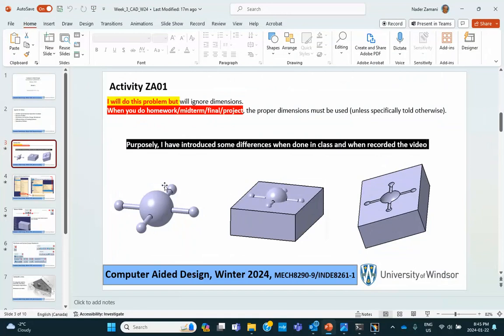So the part that we want to make is actually over here. Here is the mold, and obviously there's a gate here where plastic is injected, but I'm not going to model that. Now I'm going to do this using Boolean operation. When it comes to creating these three-dimensional parts, I use surfaces in order to create things like this.